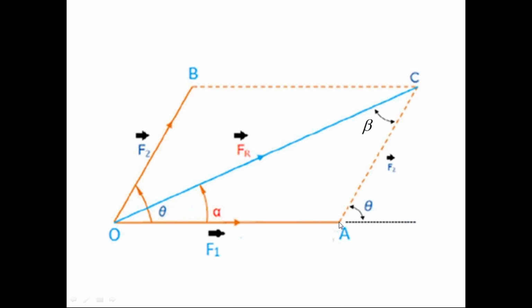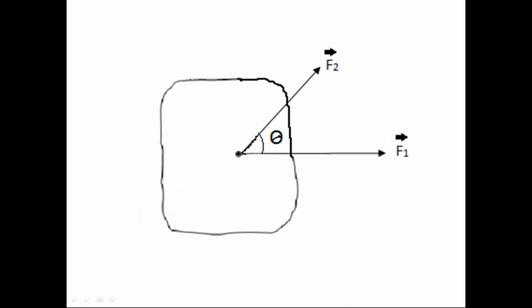Select the point A on that straight line. So this length OA is the magnitude of force F1 bar. Indicate the arrow on the line OA in the direction of the force F1 bar. So we can call this vector OA bar equivalent to the real force F1 bar. I am going to discuss with you how we can apply the parallelogram law of forces to find out the resultant force of F1 bar and F2 bar.